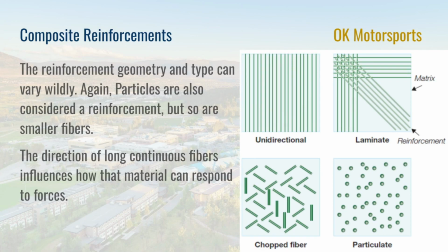When we look at the laminate, that's where we lay many layers on top of each other. You can see in that very first layer where we have the 0/90 fibers, that would be a woven material. And then the one that goes across on a 45-degree angle would be the next layer of the laminate. So you do all of those directions and you'd cover every single direction that that part would be exposed to in terms of force.